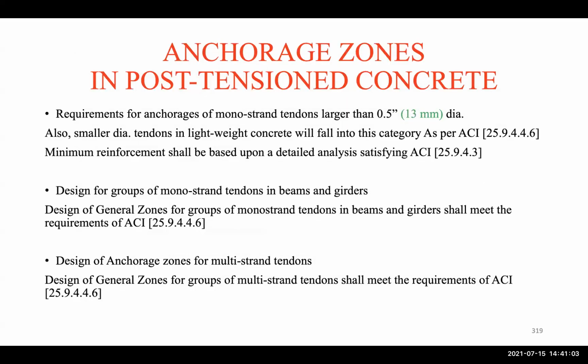I'm sorry, the post-tensioning force in the slab. Okay, so here we have also several requirements that are related to anchorage. For example, if we have monostrand, we typically see that in slabs, but groups of strands or multi-strand, we typically see more in beams. So that's designed for groups of monostrand tendons in beams and girders. So that's what I was talking about.